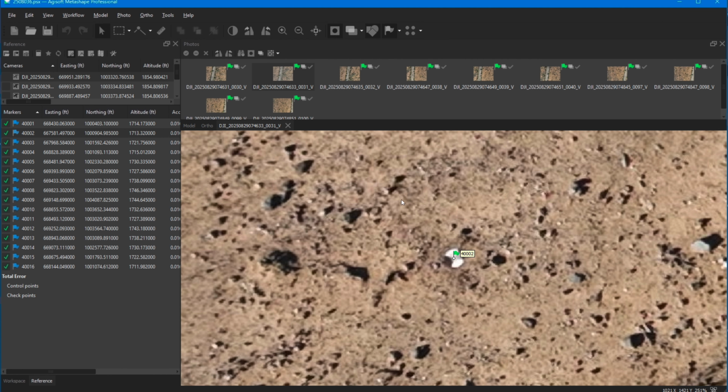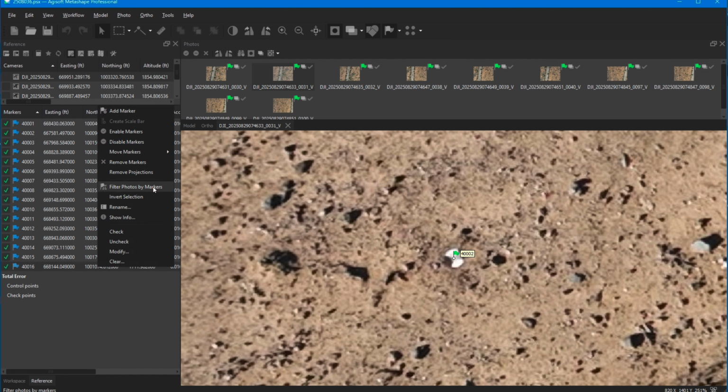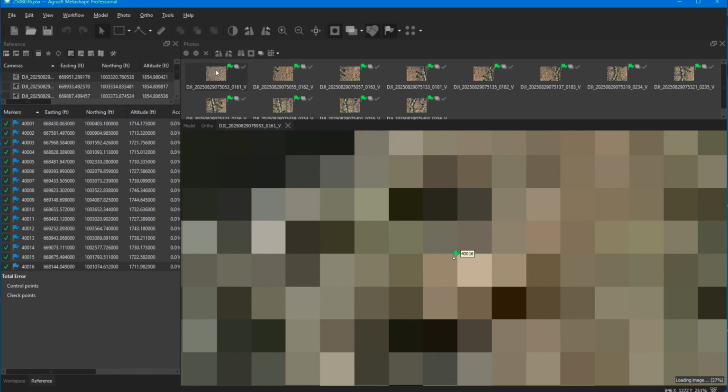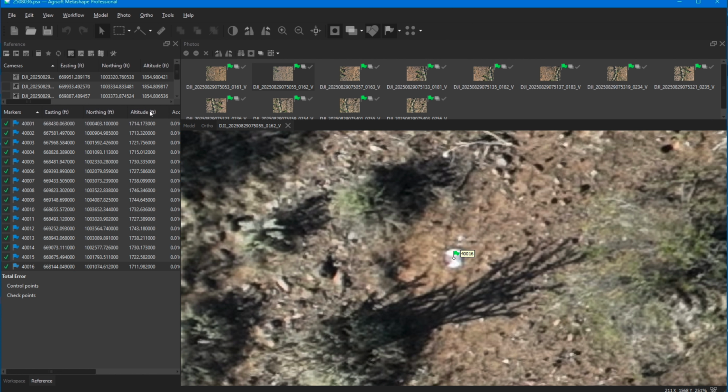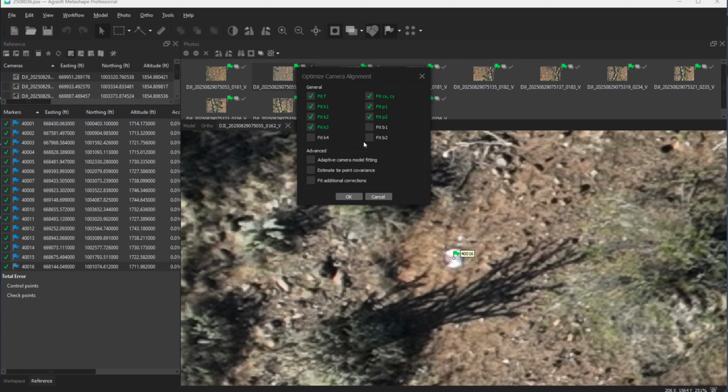What that will do then is start adjusting the imagery to fit the target. Once you get them all tagged and you walk all the way through and do every one, then you run the final optimization. And I go with the default here. I don't mess with changing any of those settings.